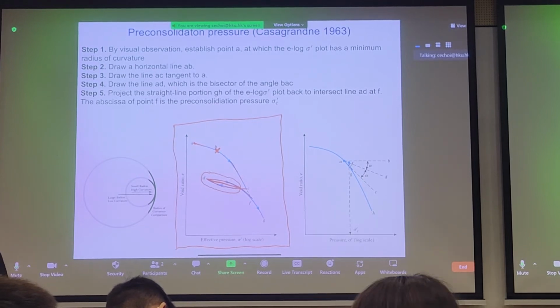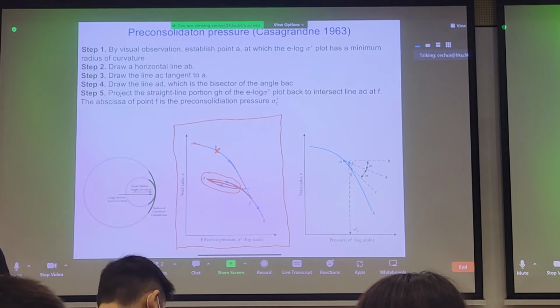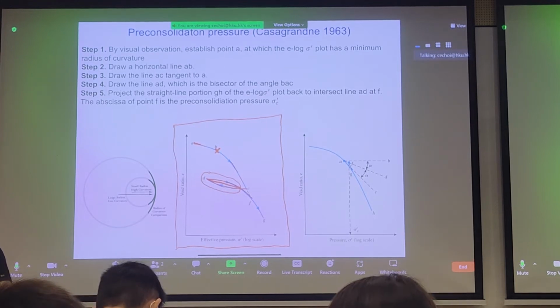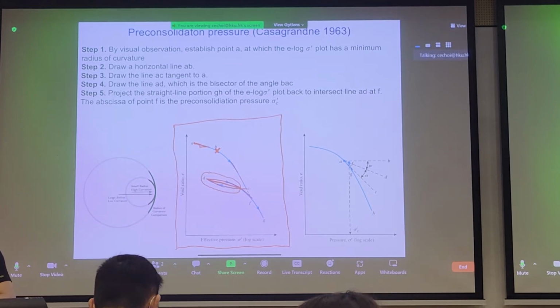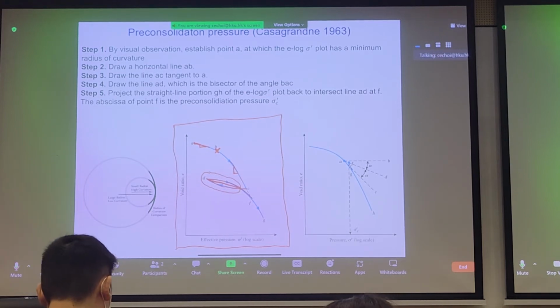But all right. So where was I before I found it stuffy? Right. So we're talking about this. So this soil in particular, you can see that it followed one type of stiffness. So there's some slope here, and then at some inflection point B, it followed another type of stiffness. And what happened in terms of slope? Well, the slope was quite shallow initially, and then it turned into a much steeper slope. And what does a steep slope mean?